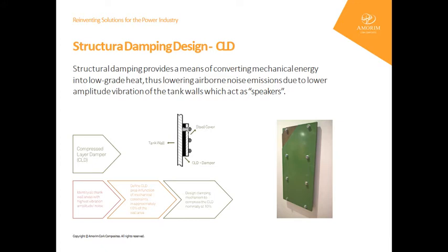Using this solution, which we can call a sandwich solution, in the first stage we are stiffening the wall, so not allowing the wall to bend as much as before. And by the incorporation of the material VC2100, again because it's inside the transformer, so immersed in oil, part of the energy that hits the wall will be dissipated by shear forces, and by doing that, the sound that goes to the surroundings will be lower.